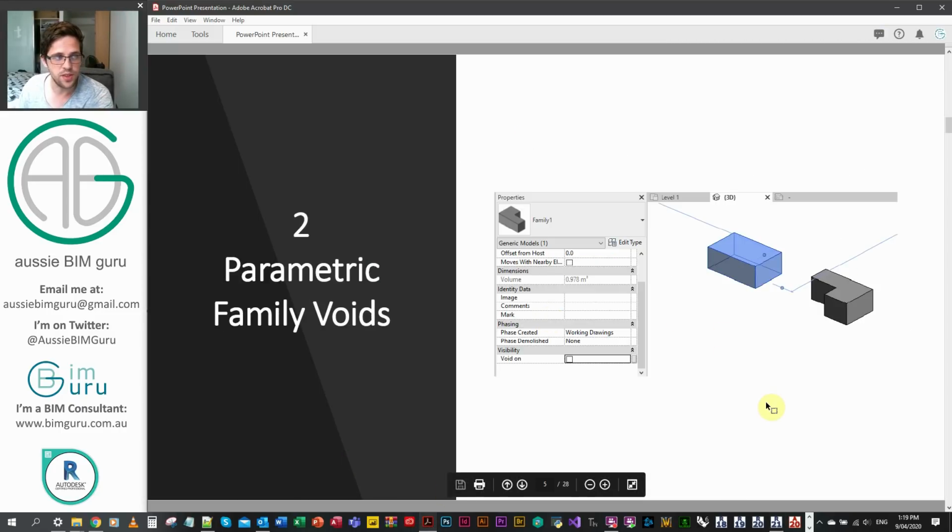The second one, which I think is great, is parametric voids in families. So the ability to turn off voids using a visibility control. Originally, we used to have to do things like put a parametric depth control on a void and only push it into geometry under a certain condition controlled by a visibility statement. So in this case, this is brilliant.